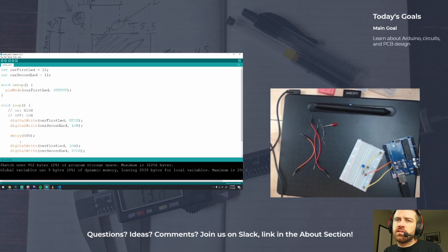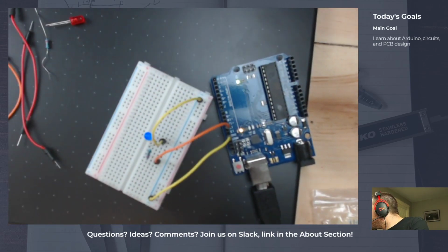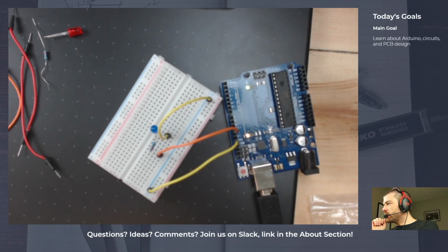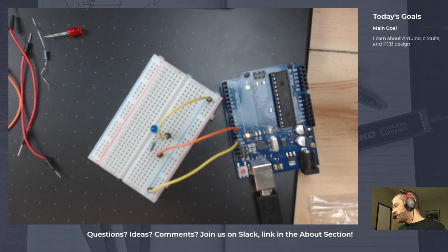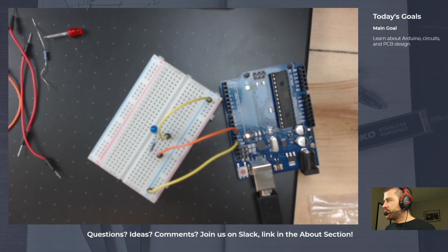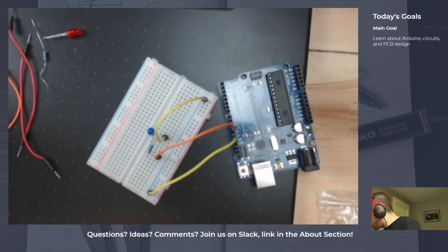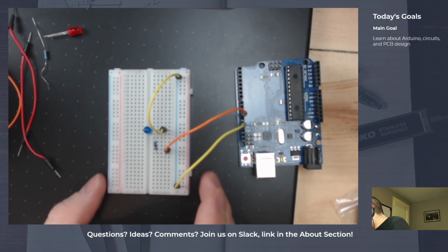and the LED does nothing. Oh, it does. That is not bright at all. I wonder if you can barely see that. But it's blinking. Cool. So we wired up one of the LEDs. So I did a little no-no. Your Arduino should always be disconnected when you are wiring it up. So I disconnected it. And now we want to connect the other LED.